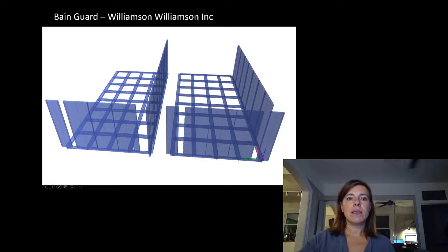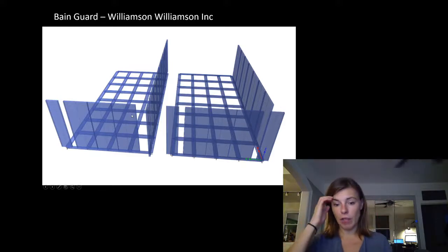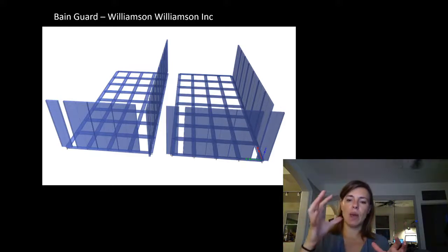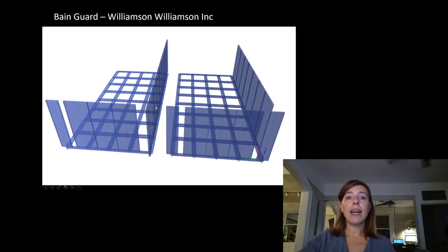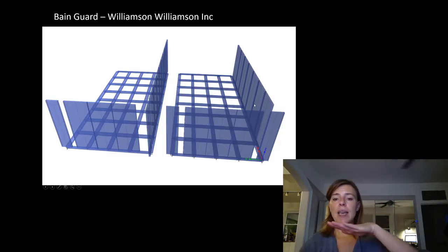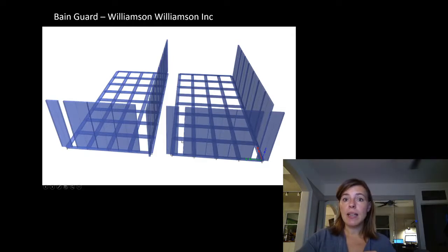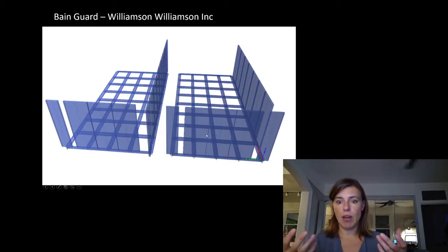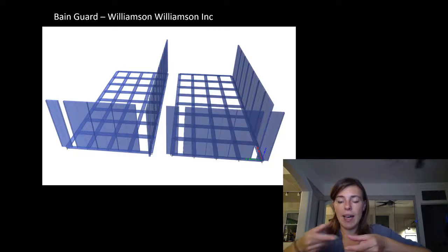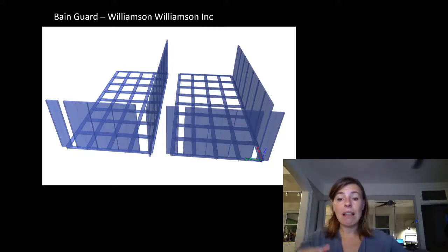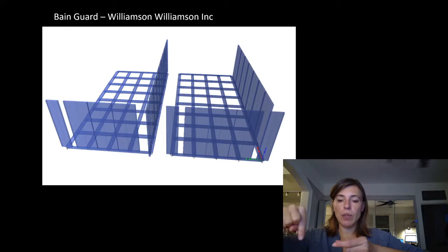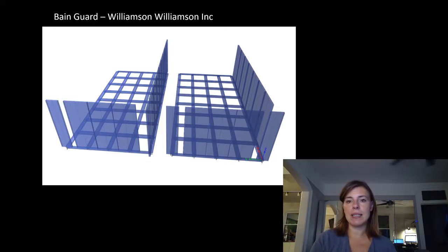One big piece of steel this size, even with the holes cut in it, A, would be too wobbly and floppy, and B, it was too heavy to get up on site. So we cut it into sections. This was laser cut, so it was a solid piece of steel with these openings laser cut out of it, and then out of those pieces, because they'd already paid for that steel, was cut again to make basically clips that went underneath that had pre-drilled holes that they screwed these assemblies together. So this was my model.